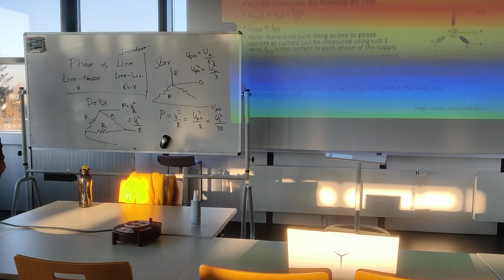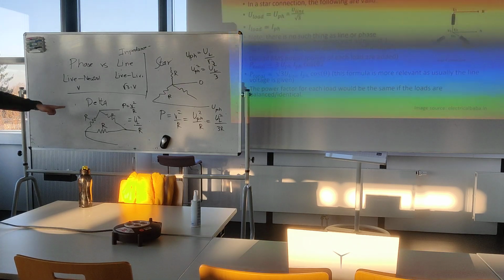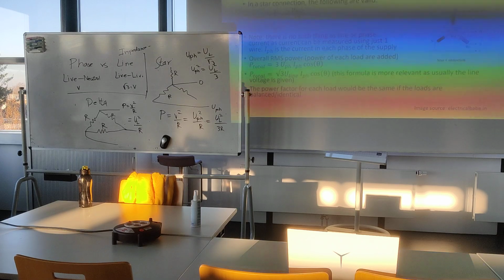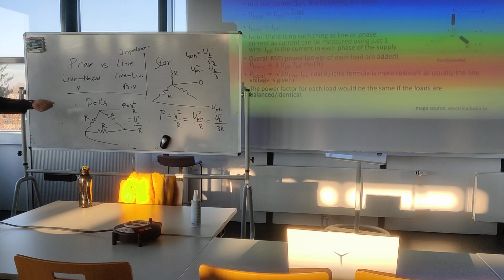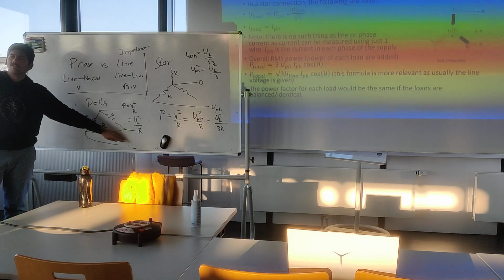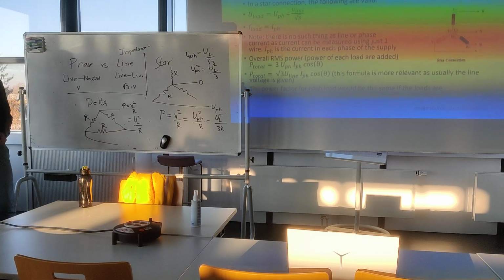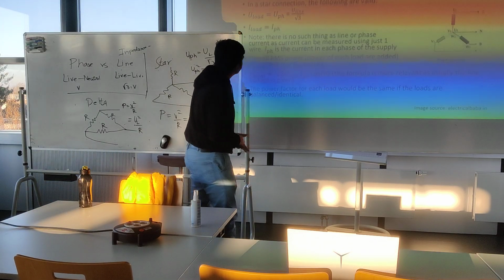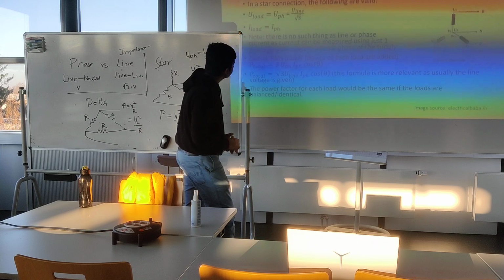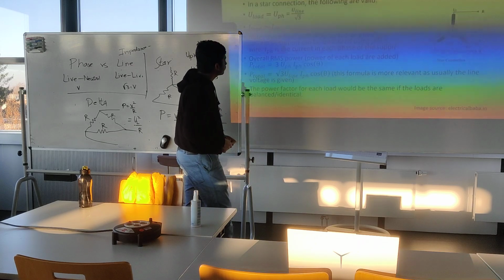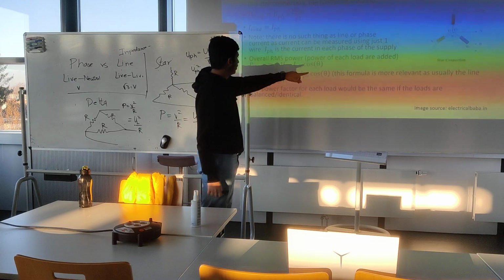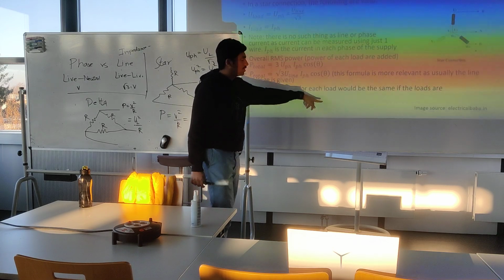That's why in soft start of motors, we use star. It has less power, so we have a slow and consistent start without any sudden jerks. And once it's running at a decent speed, you can switch to delta, which will give the nominal power. So that's what I've described here as well, I think. In these conversions, the total power is root 3 U line I phase cos theta.